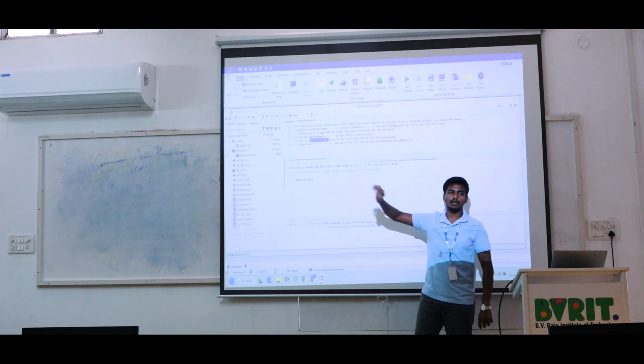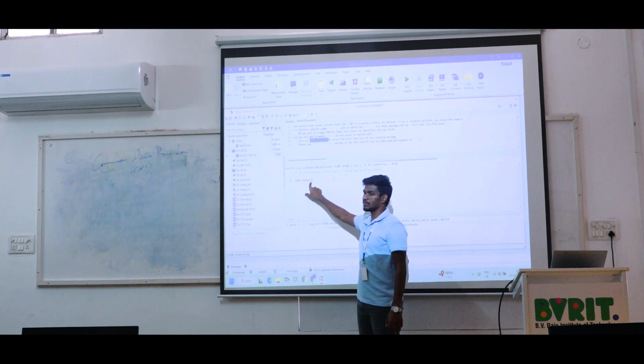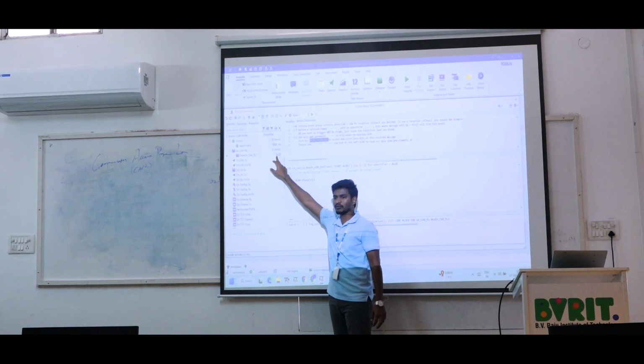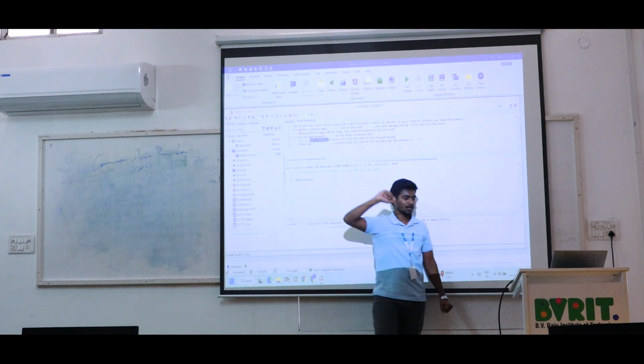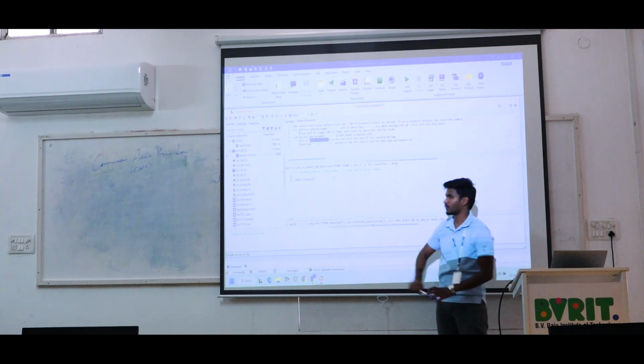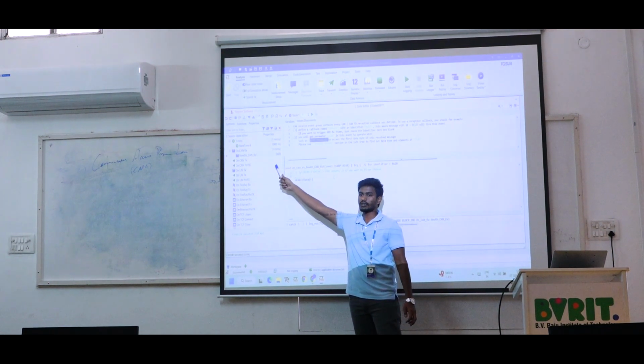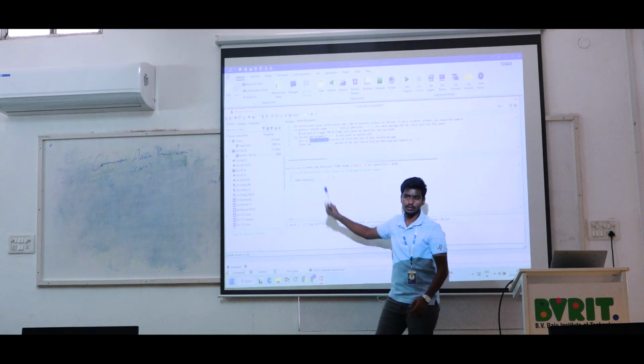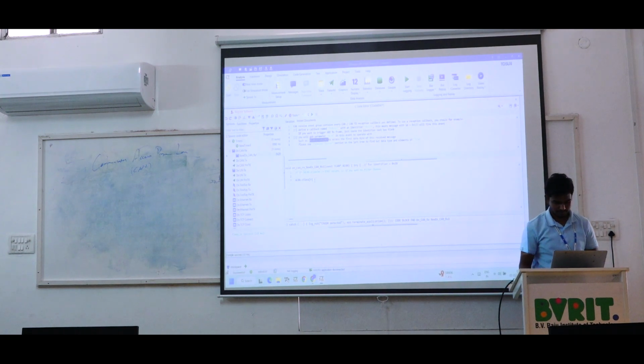So what does this line mean? The F data means the DLC data field of our particular message. Now we are working with only ID number 20, right? For this 20, we have a different kind of DLC. But this 20, I think, has 5 DLC, which means 5 bytes. So the 0 means the first byte. So I am just copying it 5 times now. So I have to change this.